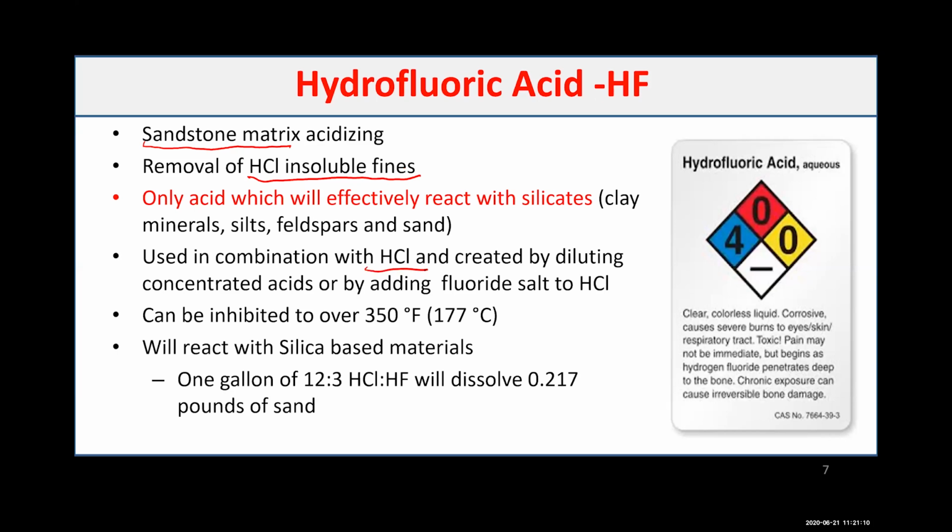The reason I will discuss in my next slides, because HF is a good acid to dissolve. However, HF develops a lot of insoluble reaction products that are not good and can significantly reduce your porosity and permeability, and make the job that you are trying to do to improve your production give you the opposite result.